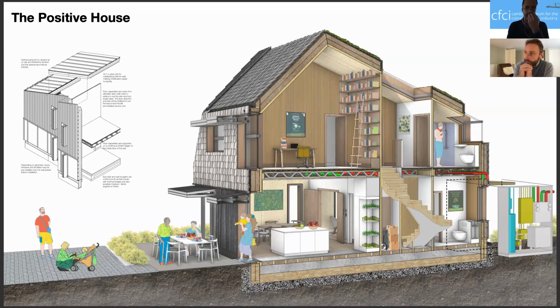So the difference here is that we haven't gone for volumetric, as I mentioned before. We found it's much better having more of a hybrid modular approach, more of a panel and chunk, we're calling it. So it's a balloon frame construction, where on the left here you've got a full external wall produced in the factory, which can then be lowered in on site, similar to the roofs. And just a very simple cassette where you impregnate the services, which can also be installed in the factory and then lowered and secured in place. So this is our approach, which through a lot of research we feel is the best option.